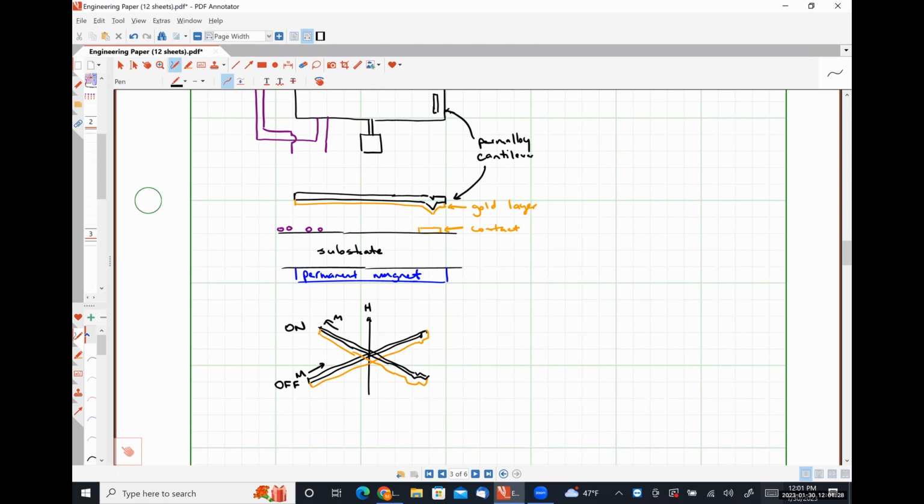Some of that is beyond what we're talking about right now. So some capacitive, electrostatic switching devices actually use a thin insulating material over one of the electrodes. And so it's not so much that electrical contact is made, it's that there are two different capacitances, because you would see the air gap in series with the insulating material or just the insulating material, and that change in capacitance is enough to drive the switching operation. So we'll talk about that probably in a week or so.